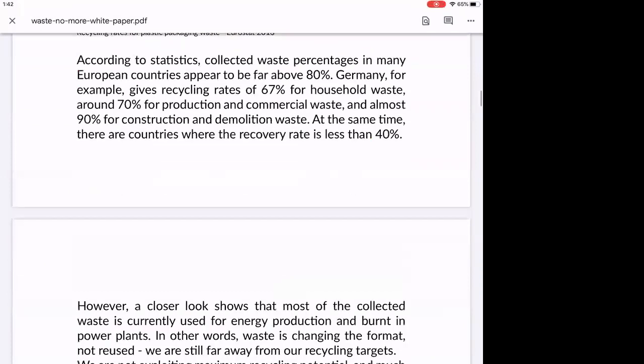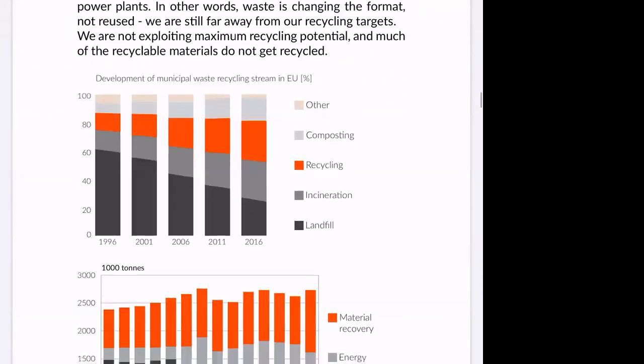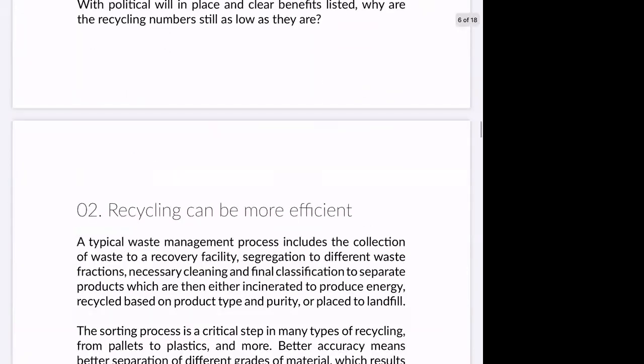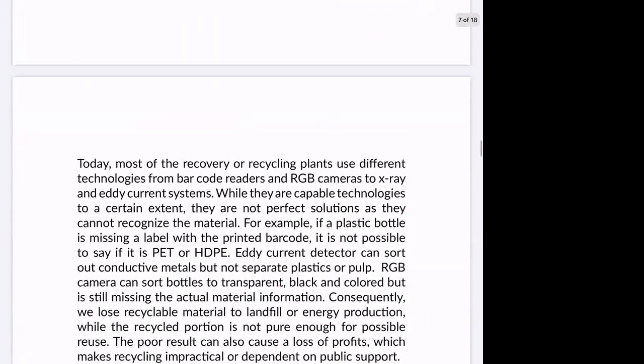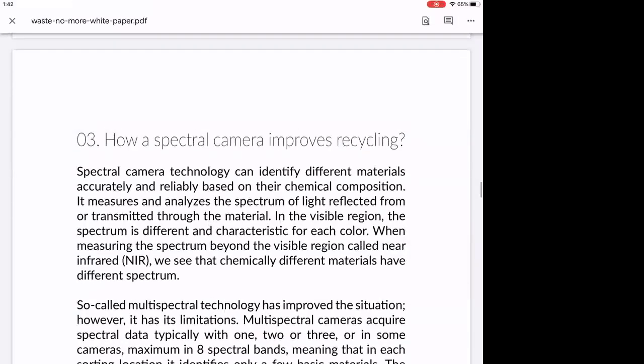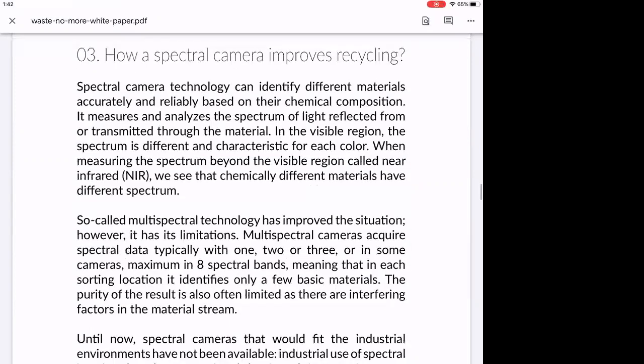It talks a little bit about the details of the recycling industry if anyone's interested, and the goals of the industry. But let me just highlight this camera. It is called a spectral camera, which you can read about here, because it not only sees the intensity of light, but also gives you the wavelength information. So if you recall, in one of the previous slides, I showed you the spectral signature is important to distinguish between the different plastics. This is a camera that allows you to essentially do that in one shot.